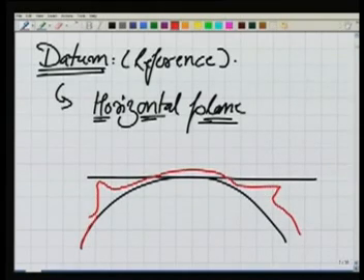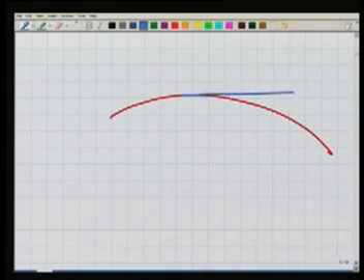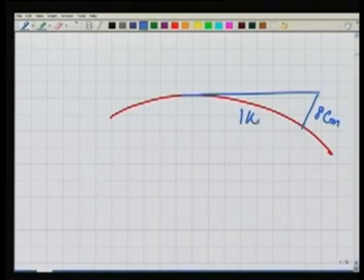Well, if the area of my work is very small, we can always take a horizontal plane as my reference, because we know it, we have seen it before also, that in my earth, the tangent from the earth deviates by 8 centimeter in 1 kilometer.